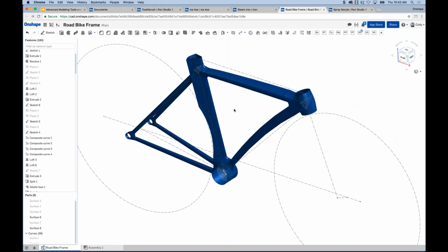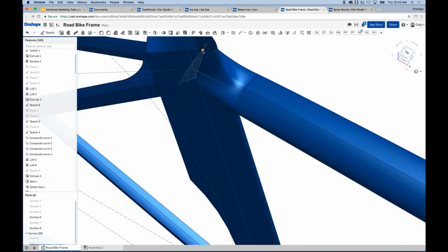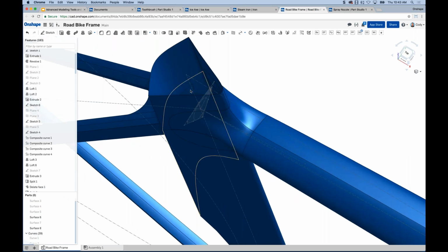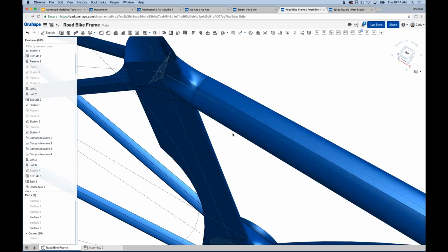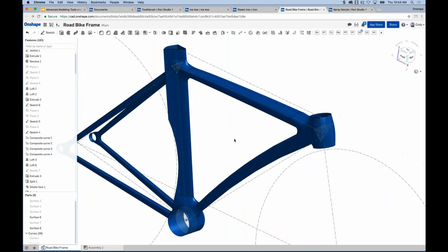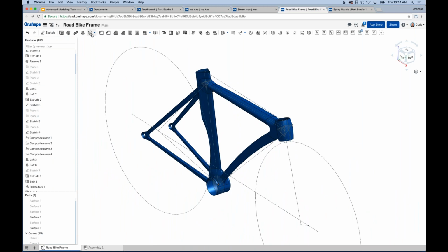The example I like to give is the bike frame, because in the bike frame example, it would have some thickness, but it wouldn't be thickened to a solid. This isn't a solid mass inside of here. I would thicken it some to accommodate the composite layer thicknesses, right? But I wouldn't want to enclose all of this and create a thick mass out of the bike frame, because that's not what it would be like in real life. So this is an example where I would use thicken.